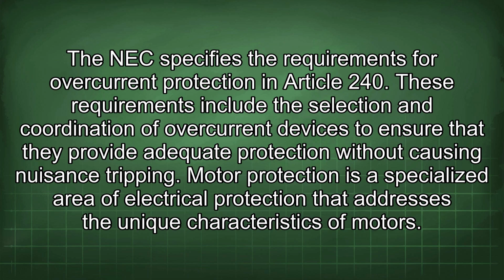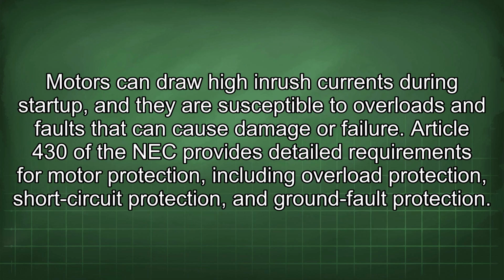Motor protection is a specialized area of electrical protection that addresses the unique characteristics of motors. Motors can draw high inrush currents during startup, and they are susceptible to overloads and faults that can cause damage or failure. Article 430 of the NEC provides detailed requirements for motor protection, including overload protection, short-circuit protection, and ground fault protection.